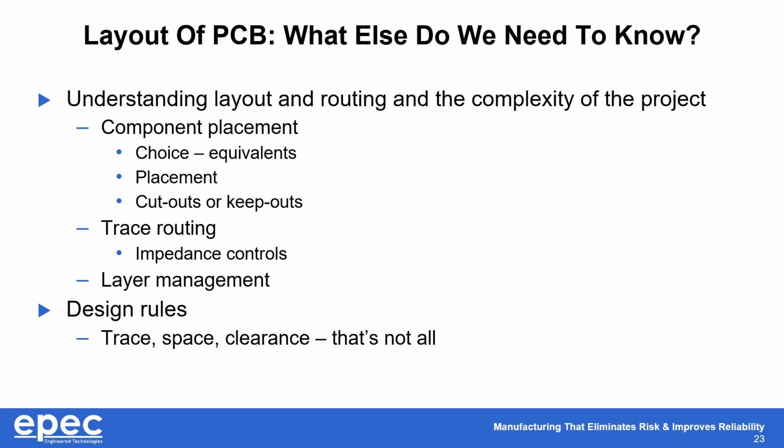So the rest of the board layout, what else we need to know, understanding layout and routing and complexity of the project. As I said, the component placement, what your choices are, your equivalents, your placement, your keep outs, your cutouts, anything about the physical finished board that we need to know that isn't part of the schematic.